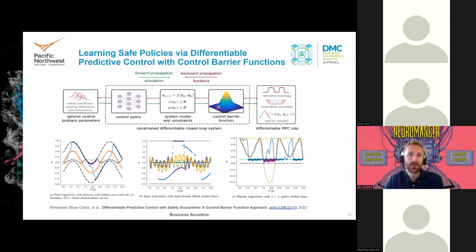And a very similar idea is to use control barrier functions, which evaluate violations of your constraints around a certain boundary of those constraints. And then you have, again, a derivative condition that needs to be satisfied in the interior of the feasible region. As you are progressing towards your constraints, it tends to be violated, and then you trigger your safety controller, which can be a projection again on the feasible set by solving some QP. So these are different ideas that can be combined with just purely differentiating your constraints and adding penalty functions.